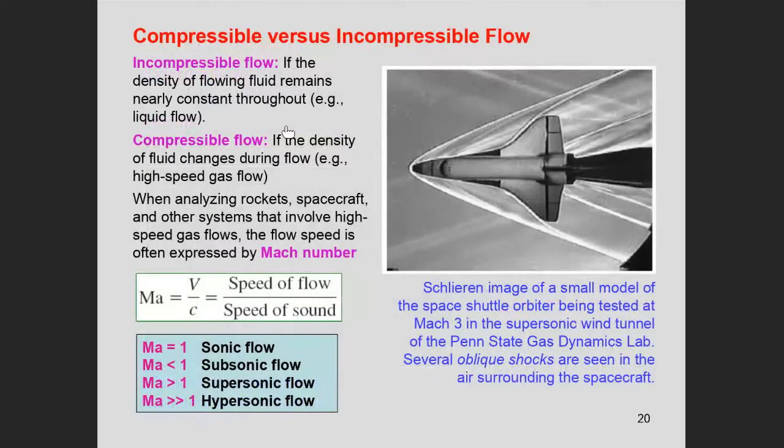Now, compressible versus incompressible. When we talk about compressibility, we are basically talking about the density of the fluid, gentlemen. There are some fluids whose density does not change no matter how much pressure and temperature they are subjected to. But there are fluids where, if you press them hard and if you heat them hard, the density will change. And therefore we have compressible and incompressible flow.